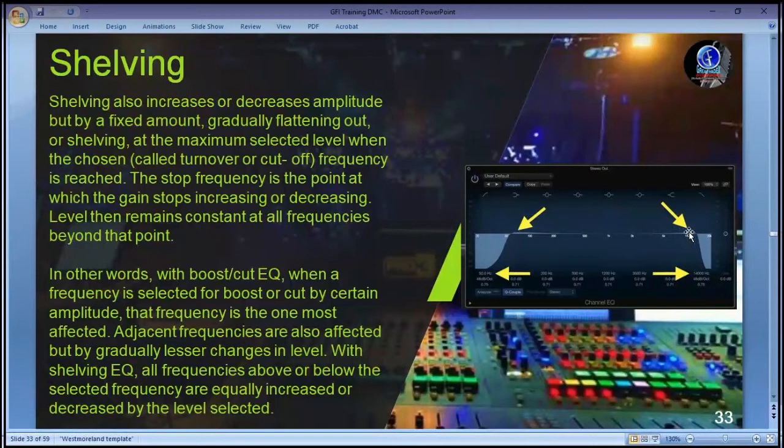For microphone voice setting, either male or female, this will accommodate it. These two frequency shelvings will accommodate it for a male voice and for a female voice. Now you can be creative with it and adjust 5K, 3K. You can cut down at around 1K. You can boost and tighten up at around 4K here. This 8K, this 10K, should be around there.